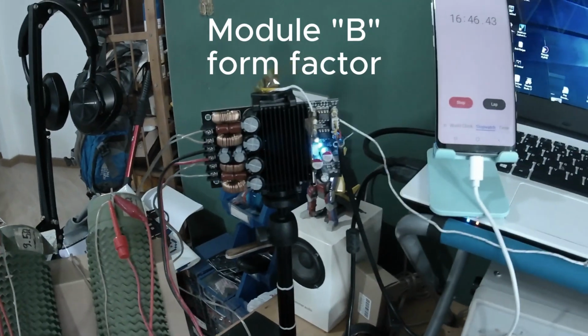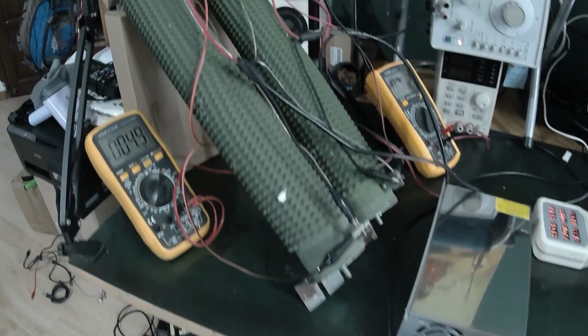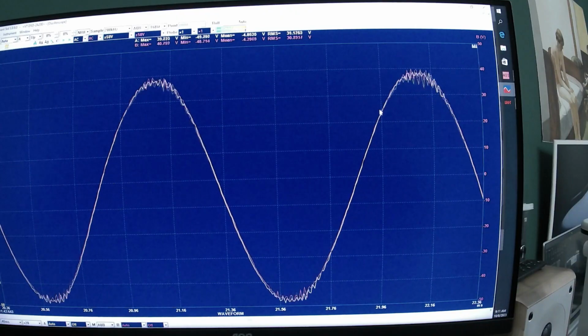So finally, I finished all the electrical performance testing of this TPA3255 right now. When I use the 48 volt 800 watt SMPS power supply, I can get about 136 watts of pure power. That is the average power, or sometimes they call it the RMS power, which is 136 multiplied by 2, like 272 watt stereo power. That is what I can squeeze from the 8 ohm resistive load.